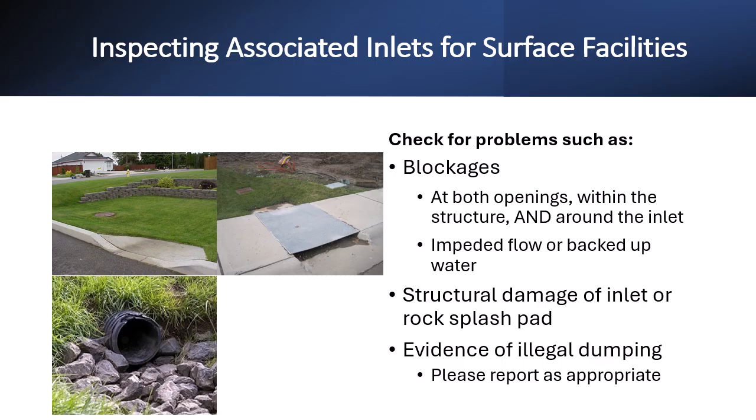In winter, snow and ice may also be problematic. Remember that blockages don't have to be right at the openings on either side, but can also occur within the inlet structure where it is not immediately noticeable. If water can't move freely through the structure, or if water is backing up, there may be a blockage. It is not enough to have a clean or open inlet structure. Blockages can also occur near the inlet, so check around the inlet as well.